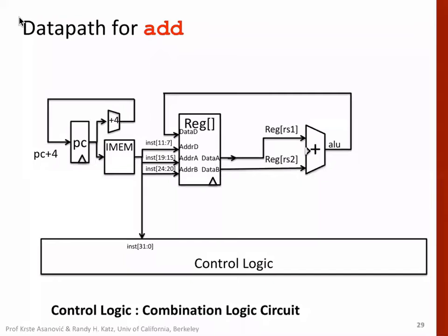So now we have shown here a control logic. Okay. And what can the control logic work on? It has to get the instruction and interpret it. So from instruction memory, we are taking the instruction, which is bits 0 to 31.